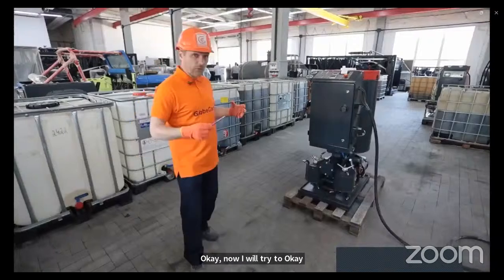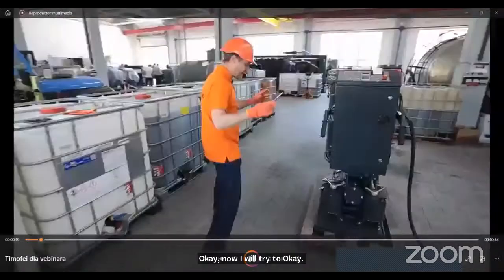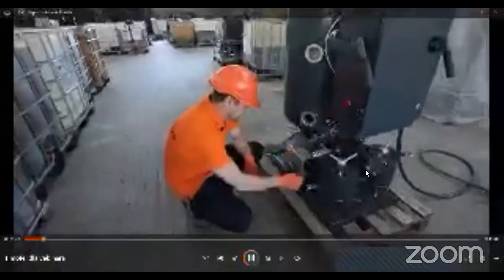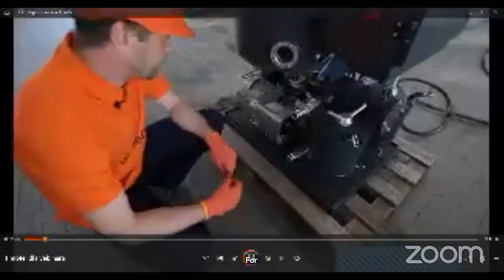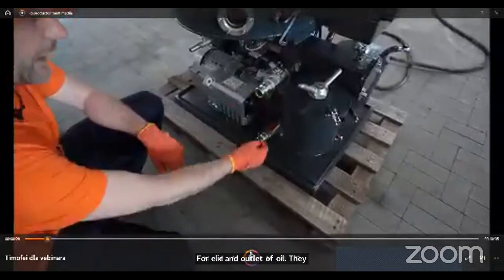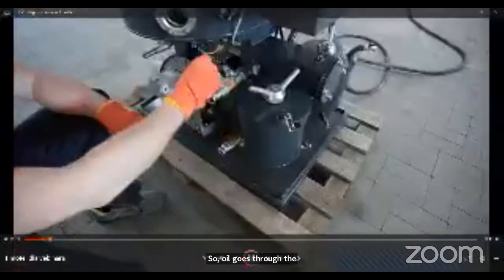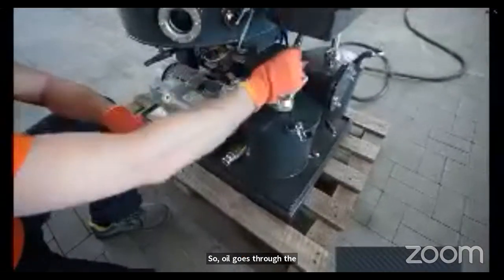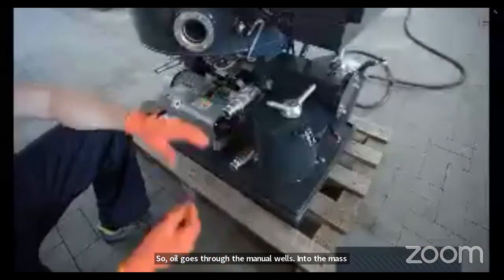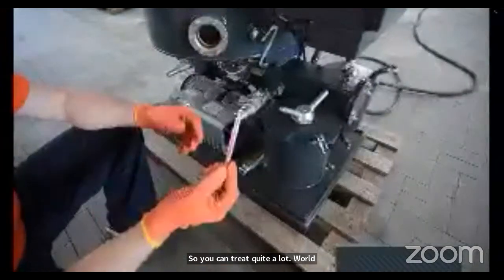Let's go through the operational principle and design of the unit. From the very beginning, here we have the ports for inlet and outlet of oil. They are equipped with fast joints of Chemlock types. So oil goes through the manual valve into the mesh filter, which is quite big and capacitive, so you can treat quite a lot of oil before you need to clean it.